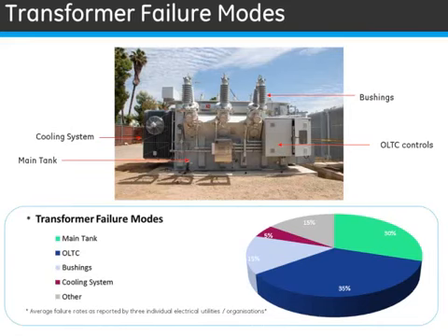When we take a closer look at these four major components, all four of these components are subjected to stress during transformer operation, and therefore they are at risk of potentially failing. The failures are not distributed evenly amongst the components, as elements of each component behave differently when stressed, and some of the elements are stressed much more than others. There are also a good amount of failures that are attributed to others. These are what we call non-detectable failures caused by either lightning strikes, severe short circuits, or operational error.